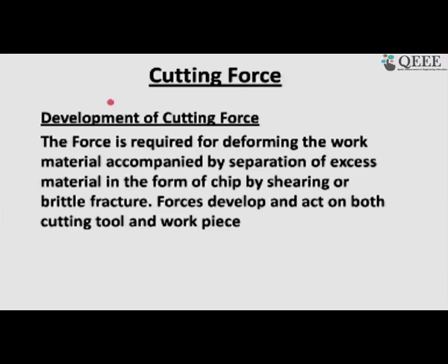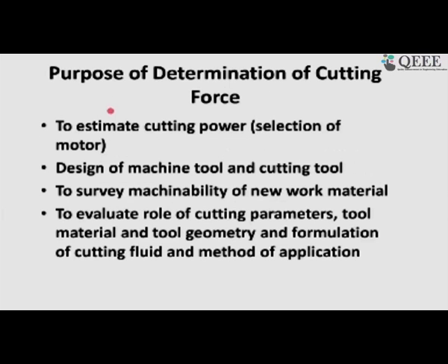In the process, we can look into why we need this understanding of cutting force at all. So, here we highlight in this slide the purpose of determining the cutting force. Obviously, the machine tool cannot work without a prime mover, and in this case it happens to be a motor. So, the power of the motor, how many kilowatts it will be, definitely one has to know the cutting force into cutting velocity, that gives you an idea of power. So, even for selection of the motor we need a clear idea of the cutting force.